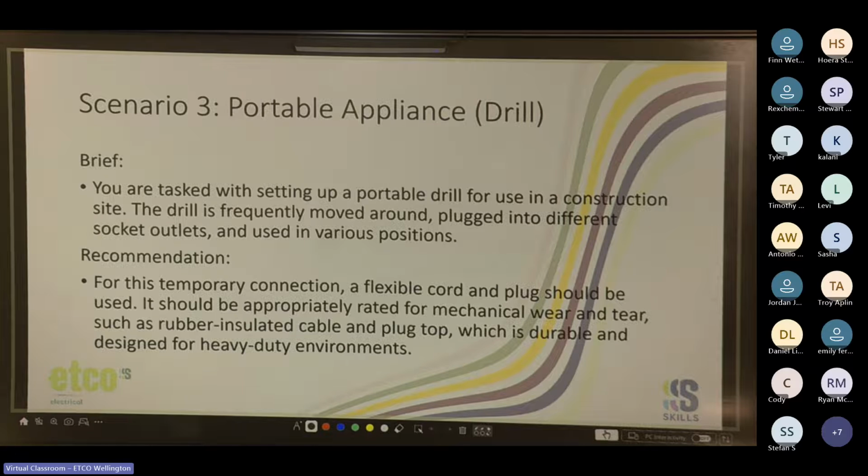Yeah, so steel wire armor cable for this. Yeah, that's fair. But yeah, just for any labor on a job site, steel wire armor cable, they'll probably just whinge and whine. So heavy duty flex, like triple layer insulation, would be good.